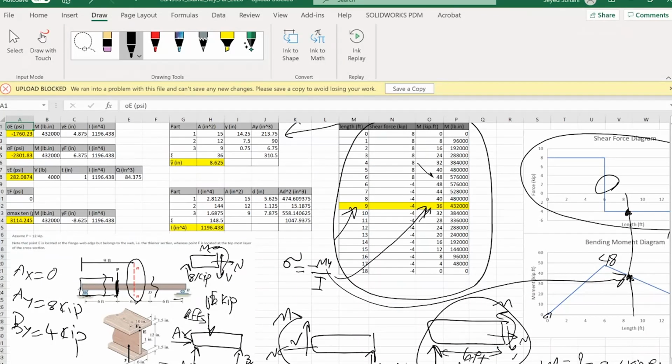First, you need to divide up a composite area, as it was named in statics, into several sub-areas whose geometry is much easier to use for the purpose of the calculations. In this case, you may have divided up this unsymmetric flange section into 3 sub-areas: the top flange, the bottom flange, and the web.